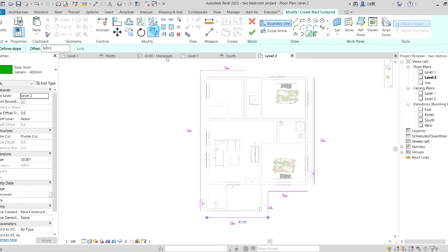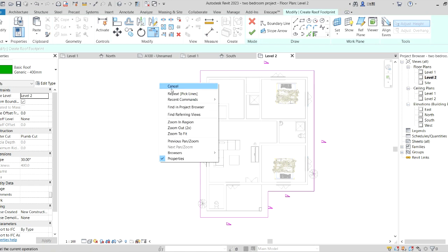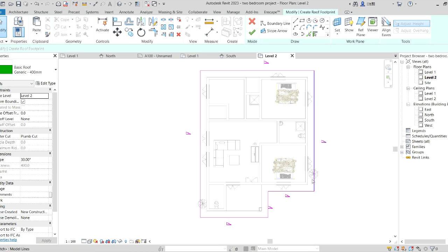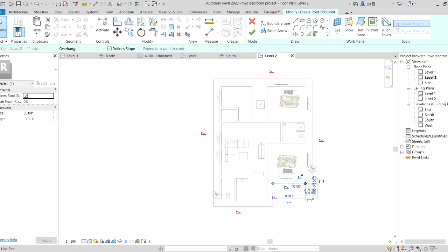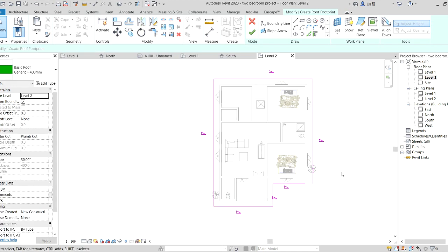So as we're done with that, we click so that all the lines will join together. If the lines are not joining, there is no way it's going to be giving you complaint. Let me give you a sample of what I'm saying. Anytime you are on this sketch level, whatsoever you are doing here, if the lines are not closed together, it's going to give you a complaint like this one now.